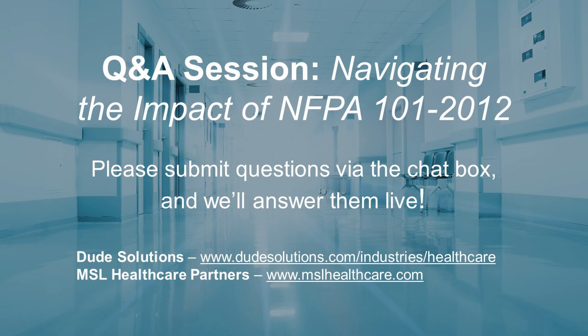Quick answer, no. And that's what's nice about this new Chapter 43. It says that if the space that we're converting is less than 250 square feet, we don't have to comply with the new healthcare occupancy requirements of the code. We can simply follow existing healthcare requirements. So that's a huge benefit for us, because often we have to convert a space from one thing to another, usually into storage, and to upgrade the walls and replace the door with a labeled door and so forth is very expensive. So this is very good for hospitals. Absolutely, could not agree with you more there.